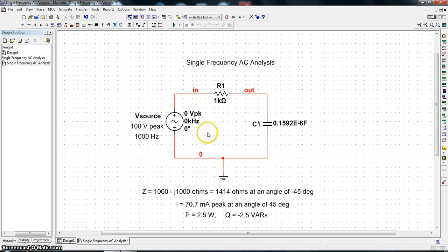Now, if one makes a calculation of the power in the circuit, the real and imaginary power, or reactive volt amperes, you're dealing with a peak value here, so the RMS value you can determine by taking the peak of the current and dividing by the square root of 2, or you can simply work with the peak value squared and divide by 2.